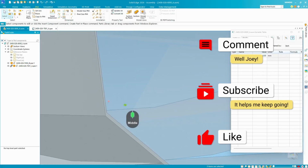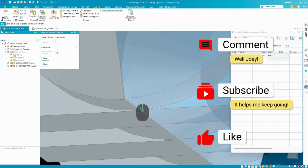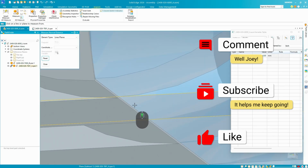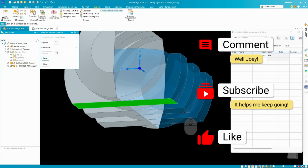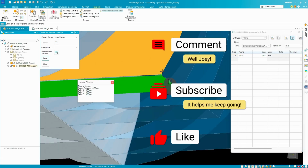And you can see there the distance between, if I go to Inspect, Measure Normal, 3D measure normal distance, and we could choose from the bottom face of the tank itself to the face of the water here is 4 millimeters, the thickness that we gave the tank.